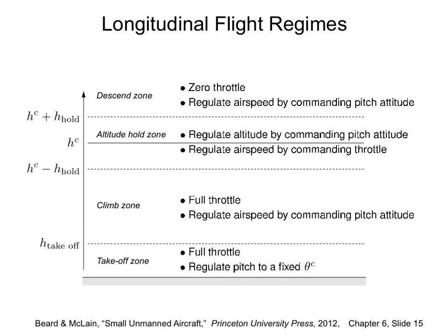Once you have written these PID loops, this is called the state machine kind of thing. You're segmenting your airspace into 3 segments. One is below takeoff, H takeoff. If your initial height is below takeoff, then you are in the takeoff zone. In the takeoff zone, you give full throttle, delta T equals 1, and you use theta.